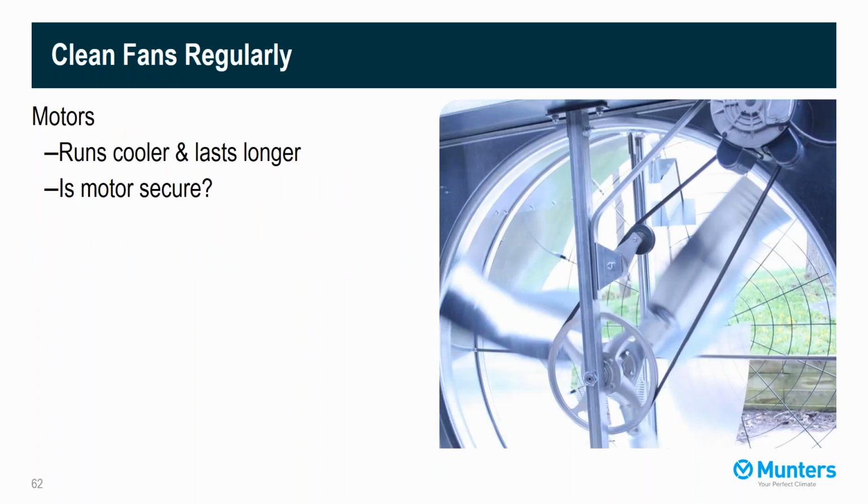We want to make sure we clean the fans, especially the motors, clean the motors off regularly. That will allow the motor to run cooler and it'll last longer. Also, while you're cleaning it, make sure that the motor is secure.